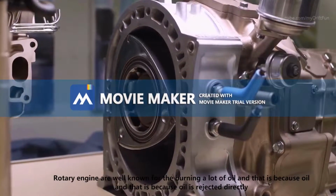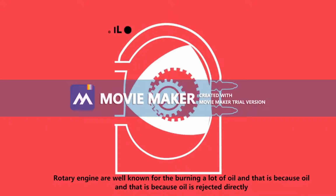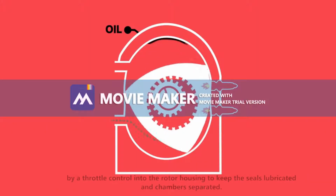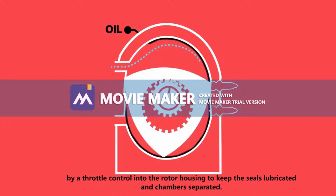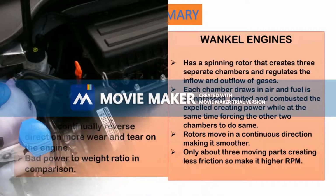Rotary engines are well known for burning a lot of oil, and that is because oil is injected directly by a throttle control into the rotor housing to keep the seals lubricated and the chambers separated.